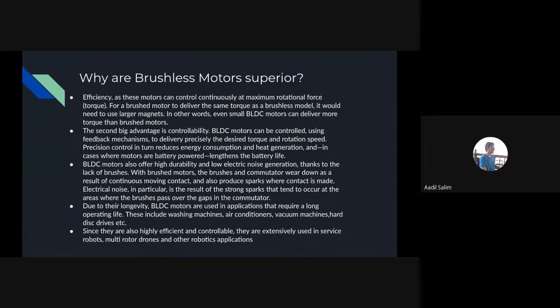For a given power, according to what our requirement is, in case of an electric vehicle, it's the drive conditions, it's the terrain, and how much torque. More torque might be needed than speed in a hilly area or such a terrain. On the other hand, if we're cruising through a highway, we might need more speed than torque. So the good thing with a BLDC motor is that this control is very precise. We can get a torque that is very close to the desired torque, a speed that's very close to the desired speed. Very little deviation will be there.